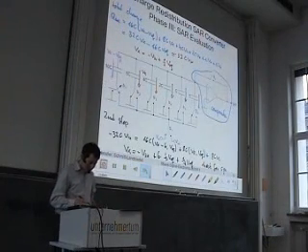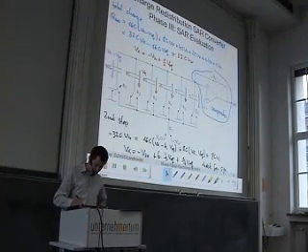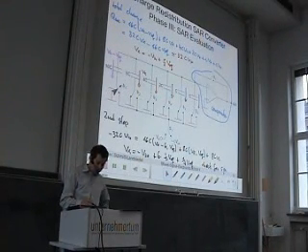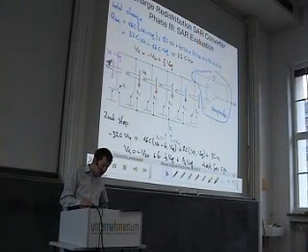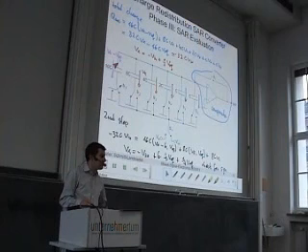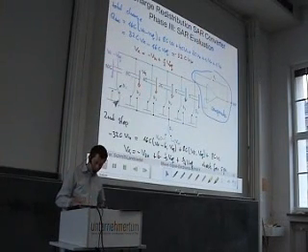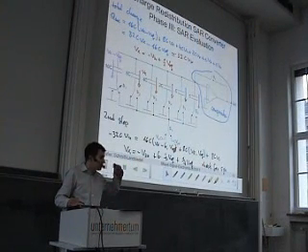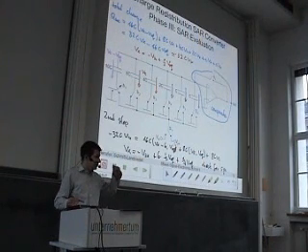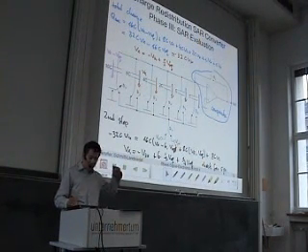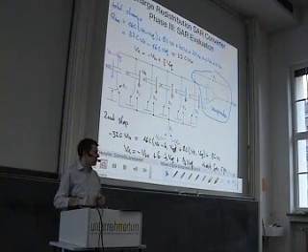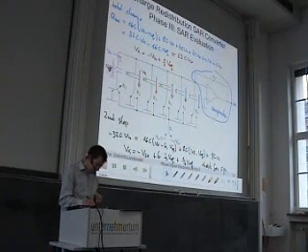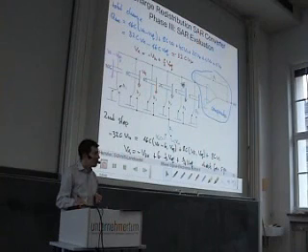Then, if we go to this phase and toggle the switch here, you see that the voltage drop here is now Vx minus Vref, because we connect this bottom node to the reference voltage. And as the voltage across the cap changes, also the charge changes. However, this charge is not dissipated to ground or to somewhere, but the change of charge on this cap is placed on the others.